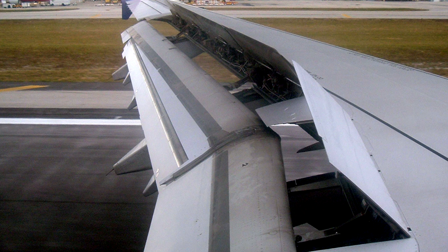Spoilers are flat panels on the top surface of a wing, which can be extended upward into the airflow and spoil it. By doing so, the spoiler creates a carefully controlled stall over the portion of the wing behind it, greatly reducing the lift of that wing section.